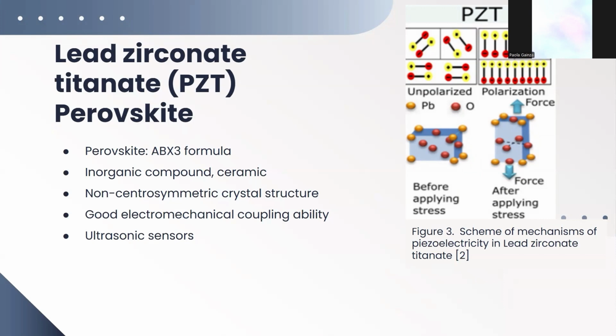When an electric field is applied to PZT, it goes through a mechanical deformation, leading to a piezoelectric effect. This energy conversion happens because of the material's non-centrosymmetric crystal structure, where the stress causes a shift in the positions of positive and negative charge centers within the unit cell.